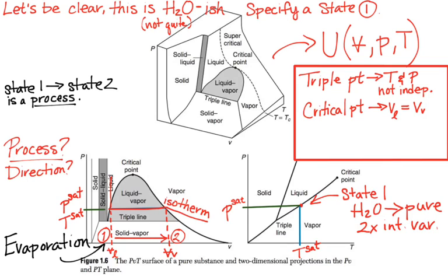It's the highest temperature and pressure you can get while maintaining these phase relationships, and that's the point where the molar volume or the specific volume of the liquid is equal to the molar volume or the specific volume of the vapor. Look at that table. Go to the bottom of that table. Look it up. See those two values are the same. It's a part of your homework anyway. You should know how to look at the diagram here and connect what you're seeing in the diagram to the table, because they're the same thing.